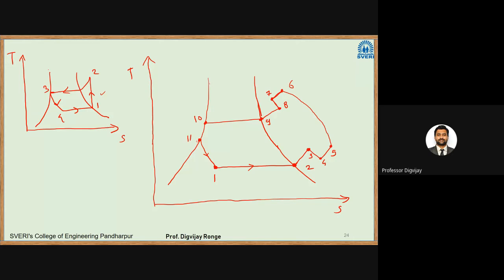Okay, I will explain again what is happening. So 1 is the entry to the evaporator. It is passing through tubes in the evaporator. It will come to point 2. Point 2 is the saturated vapor. But because of again heat transfer, that dry saturated vapor will absorb the heat. It will be converted into superheated vapor at point 3. Point 3 is the inlet, it is just starting to enter the compressor. So while entering, what is happening? There is a pressure drop at the suction side. Then 4 to 5, again temperature rises because it comes in contact with the cylinder walls of the compressor.